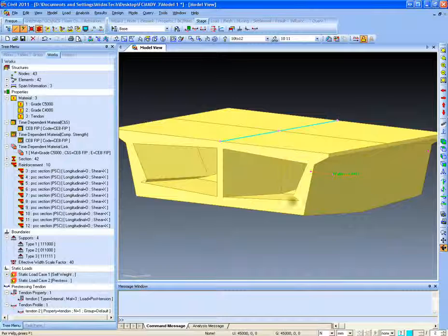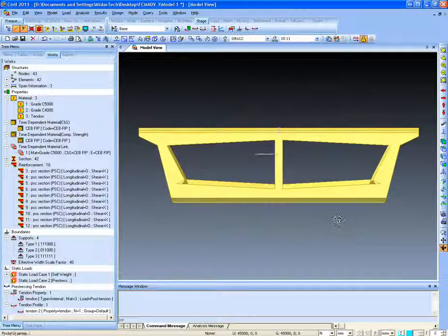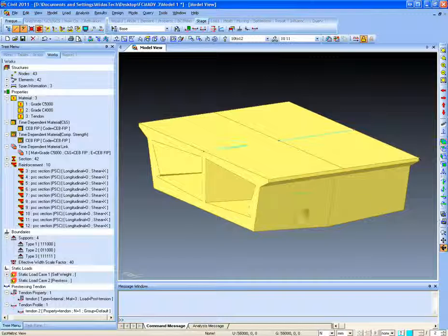I have defined the tendon in the web portion very easily by defining the rotation of the tendon as per the x-axis, and I defined certain offsets. So what I did, I defined the tendon here and provided it an offset and rotation as per the x-axis. So this is how the tendon inbuilt geometry profile definition dialog box can be used.